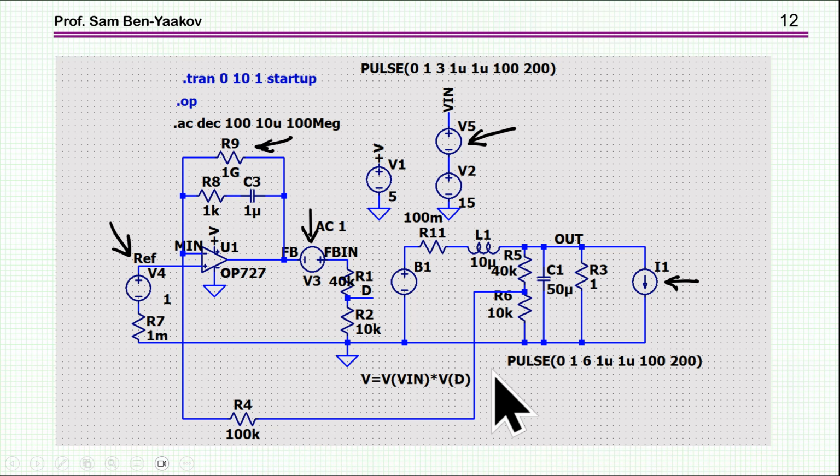I have here an average model of a buck converter. Here is the buck section here, inductor, capacitor, and load. And it is driven by a behavioral source, which is the input voltage, that is the DC, times the duty cycle. So this is the average voltage that you'll see, say, the midpoint, except that here we're talking about average. There's no pulsating here. It's only the DC component.